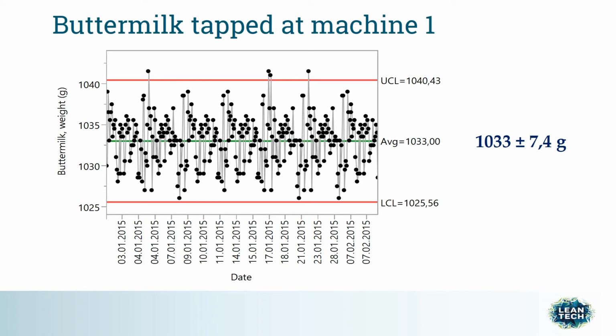So you can have some warnings when the control limits are increasing, getting wider, because this can be due to wear. You can also use statistical process control and control charts if you want to check the effect of an improvement. If you did a change to your process and you want to see the effect, you can calculate the control limits before the change and after the change, and you can find how much the change affected the process.